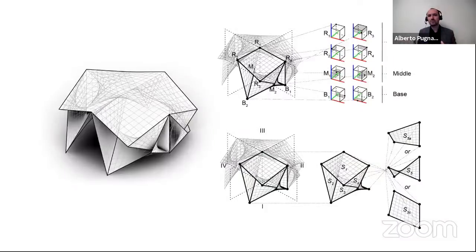So now we are at the stage in which I said, why don't we parameterize the church so that the invariants of the parametric model refer back to the 3 original design concepts rather than the final geometry? So I wanted to push parametric design to generate new topologies of this church during the structural optimization process, and not simply variations of the same topology by deforming its shape. So we used 8 points to define the edges of the hypers in 1 quarter of the structure, because we preserved the symmetry of the original design. And then, of course, there are only 3 options that remain for the 5th hyper, which defines the clerestory window.